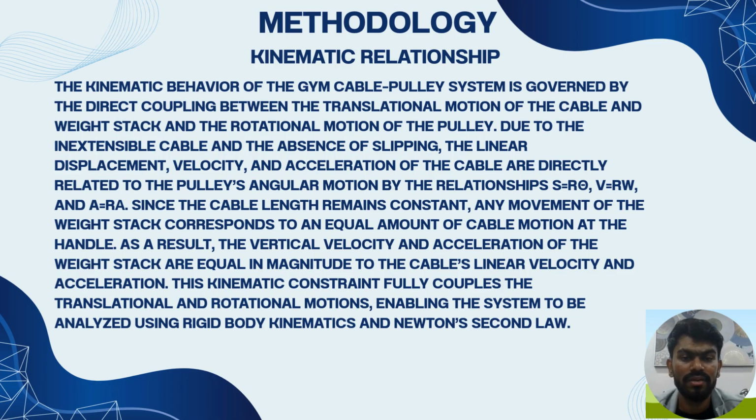Next is the kinematic relationship. The kinematic behavior of the gym cable pulley system is governed by the direct coupling between the translational motion of the cable and weight stack and the rotational motion of the pulley. Due to the inextensible cable and the absence of slipping, the linear displacement, velocity and acceleration of the cable are directly related to the pulley's angular motion by the relationships s equals r theta, v equals r omega, and a equals r alpha.